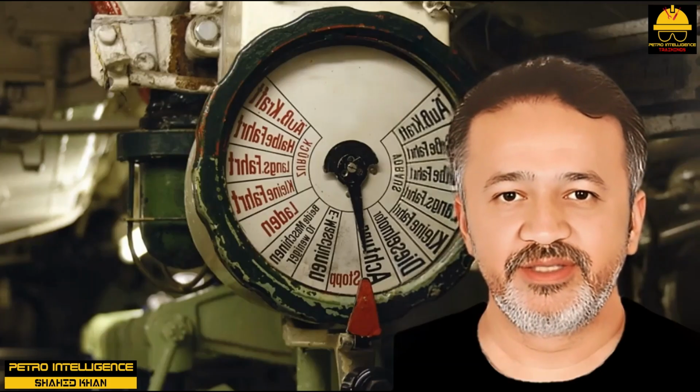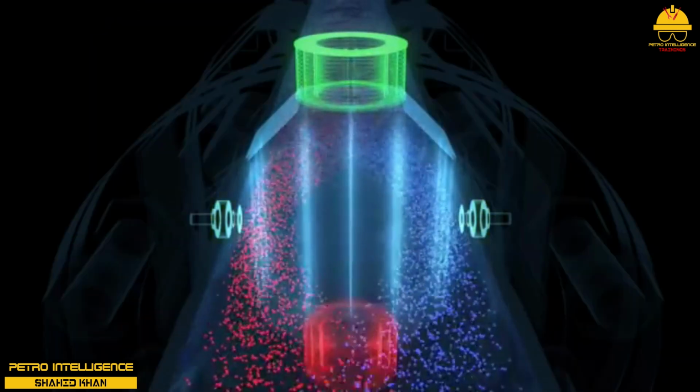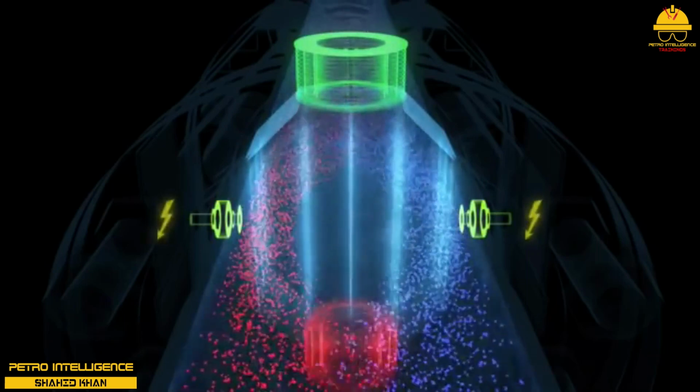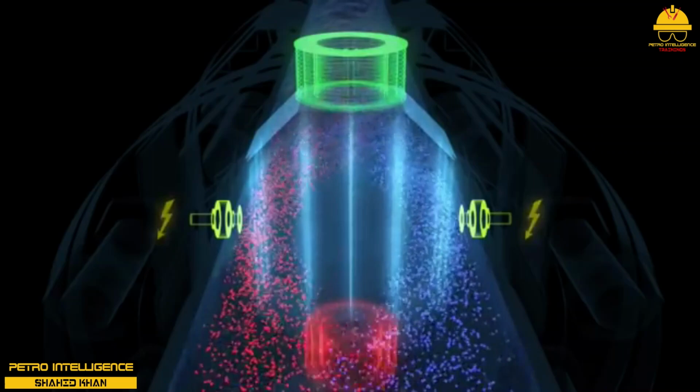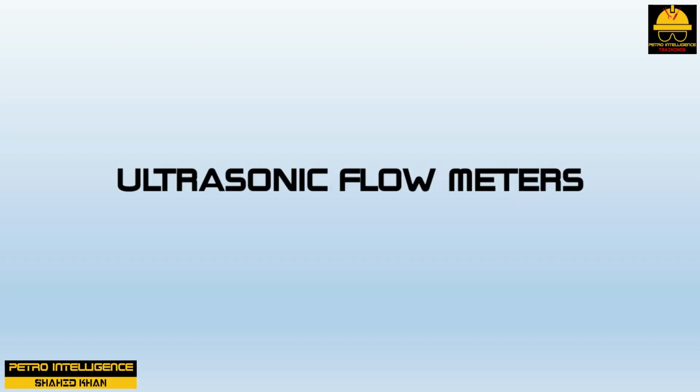Magnetic flow meters. Magnetic flow meters measure flow velocity based on the voltage created by the fluid flowing through a magnetic field. This type of meter is very effective for toxic or corrosive fluids because the fluid stream does not contact the measurement device.